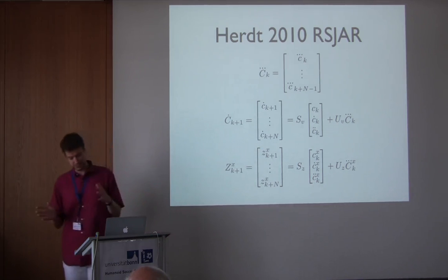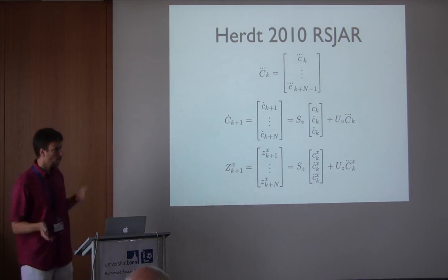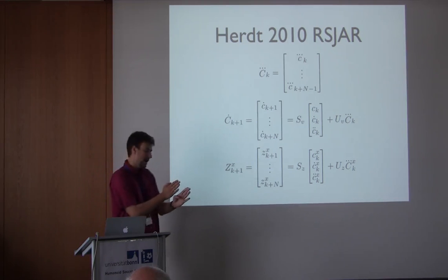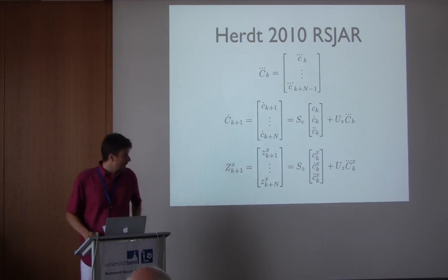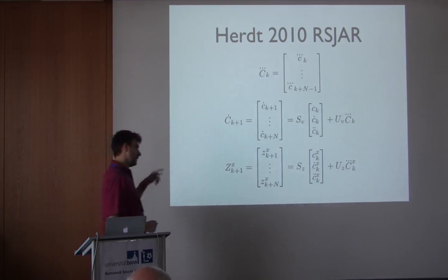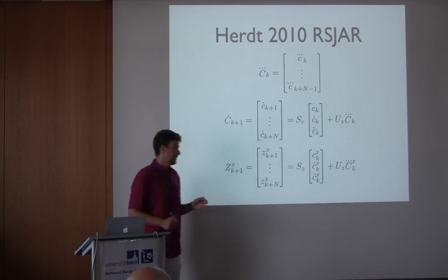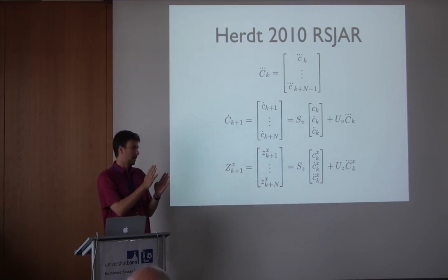Cubic splines can be represented in different ways. One way is to say I have control positions for my n steps. Another way, the way we chose, is to say that it's in fact a piecewise third order polynomial with constant third derivative, so constant jerk.